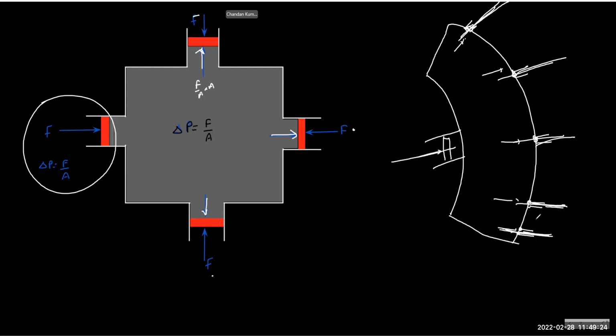Everything is designed with the same Pascal's law. Most sprayers or sprinklers use Pascal's law and the Bernoulli equation. Of course, we have two steps. One is the creation of pressure, which gets transmitted, and then the drop of pressure leads to the acceleration of the liquid. That is the Bernoulli equation, which we will study later on. You decrease the pressure, and that loss in pressure becomes gain in speed. That is called dynamic pressure, and the pressure which I'm talking about now is called static pressure. Later on, we have to differentiate the two terms.